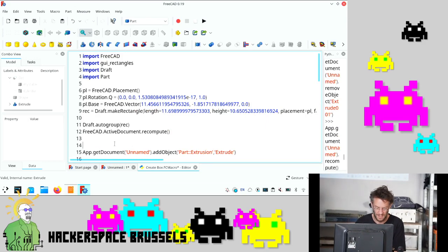What we did here is create a FreeCAD placement. A FreeCAD placement is basically an object that contains a position and a rotation, and all objects have one. So if you change the placement, you change the position and rotation of the object only, and it has no influence on the internal shape of it. So you could have this table, and you just change its placement, and you can position it in space without having to recalculate its geometry. So this is our FreeCAD placement. Here a rotation is calculated, but you see that this is actually 0 because it's a very, very small number.